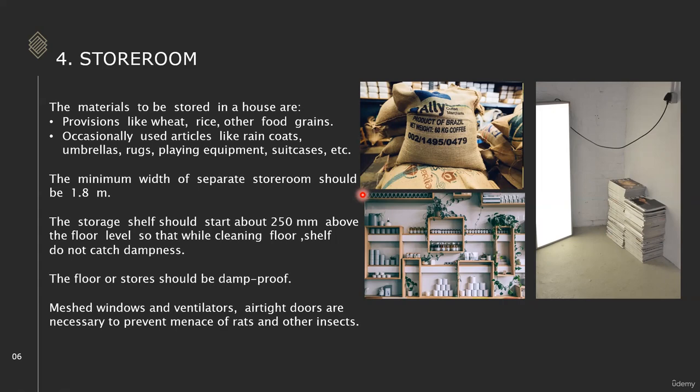The storeroom should be designed like that. The space should be minimally used, and the purpose will be more. The minimum width of the storeroom should be 1.8 meter, and the storage shelf should start about 250 mm above the floor level, so that while cleaning the floors, shelf do not catch the damages.